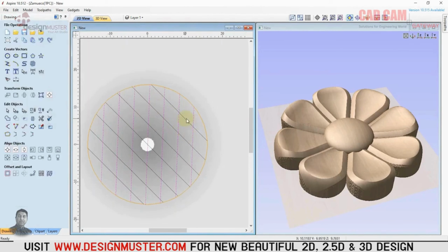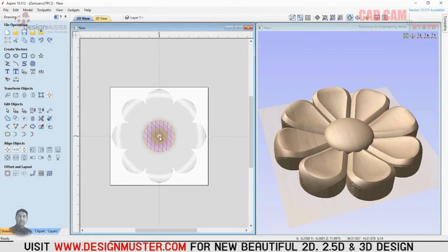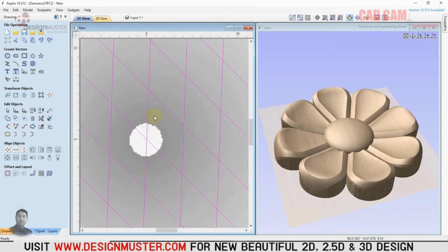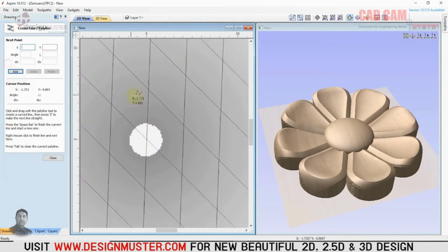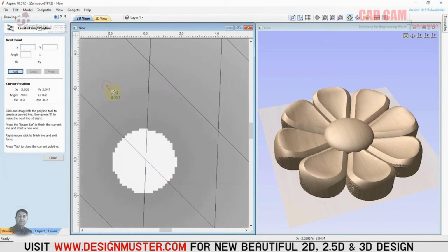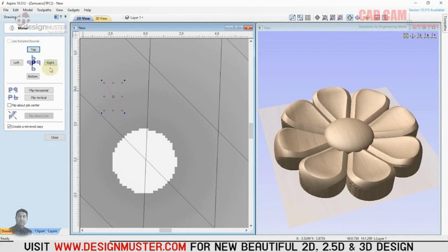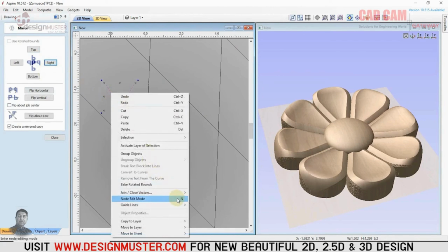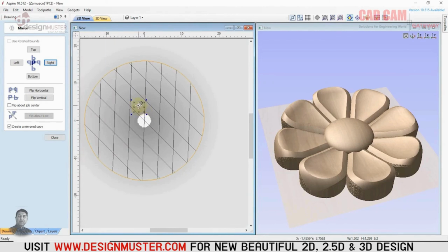Close it. Now you have, look closely, from this point here to this other point, all these various objects have now come into view. I deselected this item and then grouped them all together using the Ctrl-G shortcut. And after that, you will need to create a cross-section right here. See, I've drawn a diagonal line in this area, measuring approximately 1.5 millimeters in length, and mirrored it to the right side. After setting both of these elements, you will join them at the end, and now we have their cross-section.